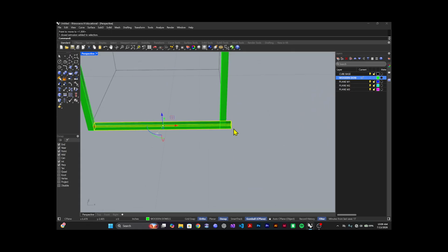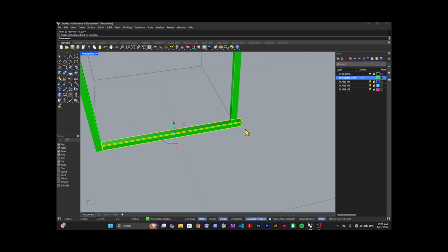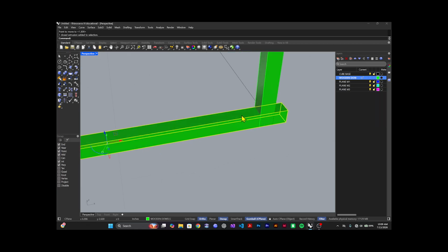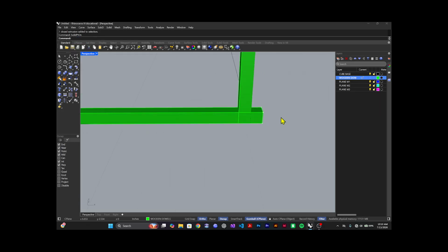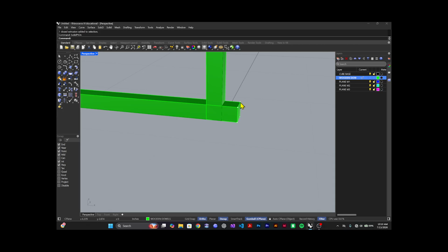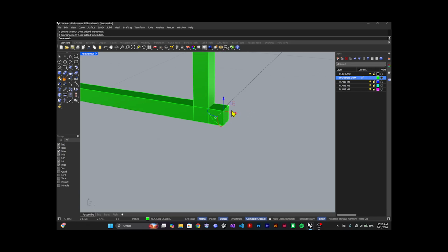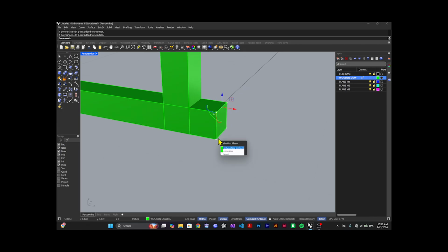So now what's happening? It's bigger, or it's longer than it should be. This guy should stop right here at this intersection. So what do we do? I'm going to select it, and I'm going to type solid points on this guy right here, and then I'm going to select these four points. To select multiple things at once, you guys can click on the first one, press Shift, hold it, and then start selecting the rest of them. So I want this point and this point, right?